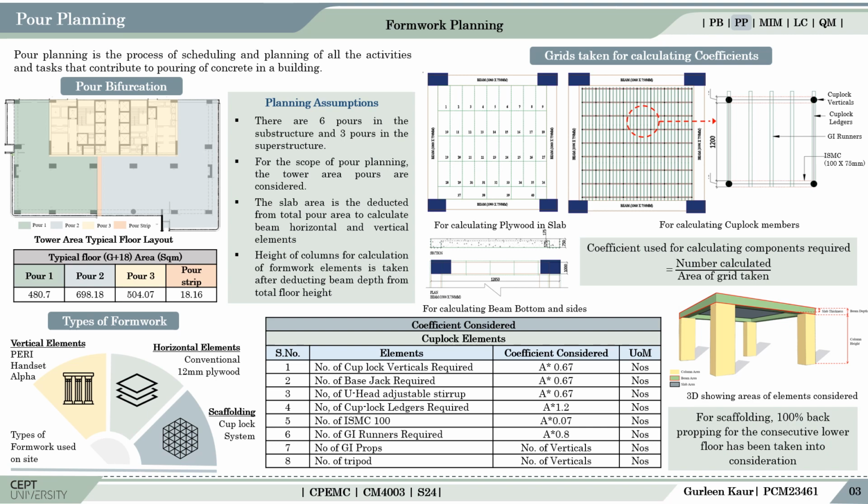For the derivation of the same, a fixed area on site was observed and respective grids were prepared. The components in the grids were counted as per the actual site observation. Slab and the beam plies have been calculated separately. For the slab, only the slab bottom plies were counted, and for beam, the beam bottoms and the beam verticals were counted separately. For the beam verticals, the outer and the inner end depths were considered, deducting the slab depth on the inner end.